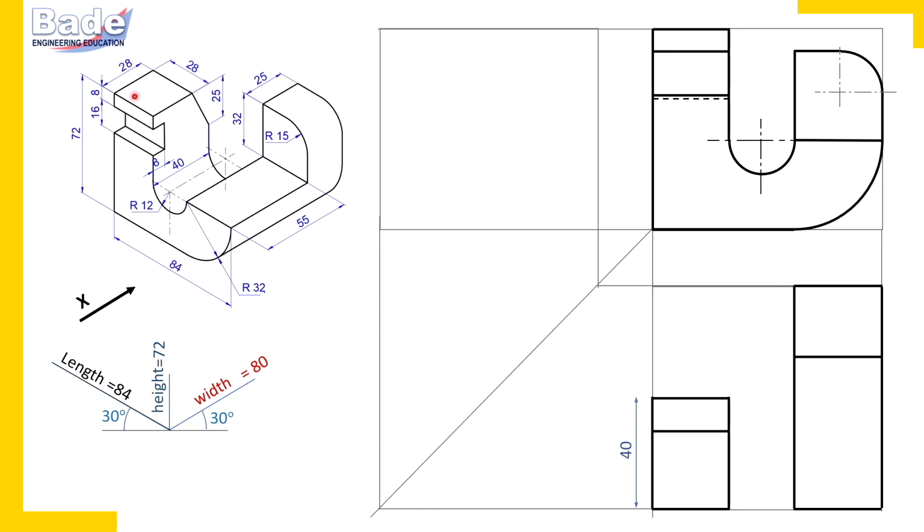So here it is: horizontal surface and then inclined surface, which is visible from top. Now let's proceed. Semicircular slot. It's an opening semicircle, or you can say this semi-cylindrical surface. In front view, it shows its semicircular shape. So of course, in the top view, it is a rectangle, and in the side view also it is a rectangle. Let's complete the top view.